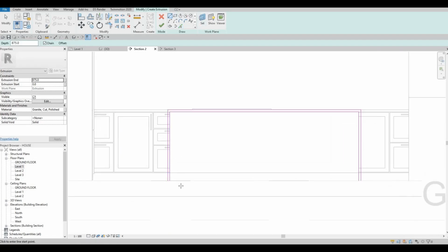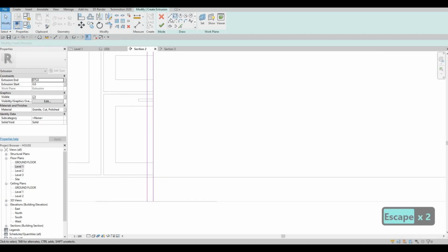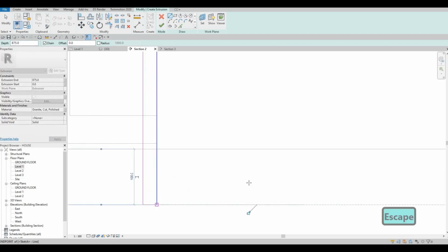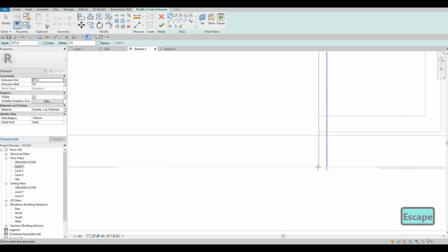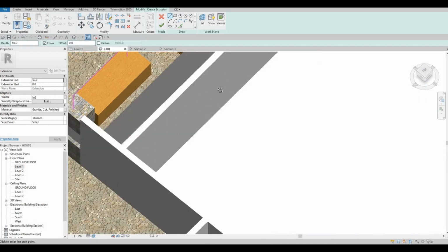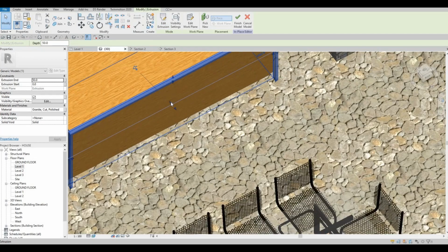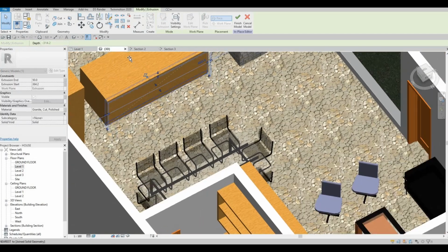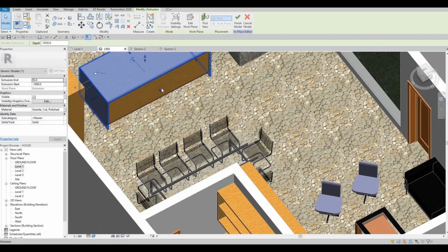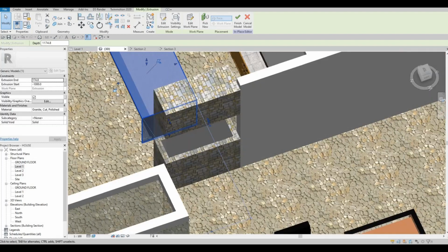And then here just select, press escape first, and then select this one so that we don't have to offset there anymore. And then here let's do an extrusion of 50 first. Click apply, go and do right here under 3D, click finish, and then now we just need to manually add this one at the back, and then in the front we need to add some of that.